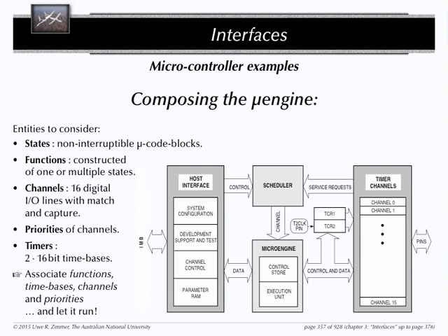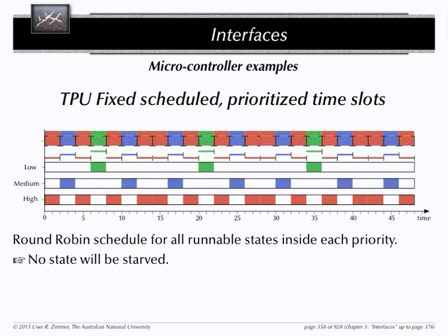But before we can calculate how long things now take, down to individual clock cycles, we need to understand an important module of this time processing unit, namely the scheduler. The scheduler is a bit of a weird one. It's a round-robin scheduler, which is very weird for a time processing unit, for a real-time environment. A round-robin scheduler with priorities.